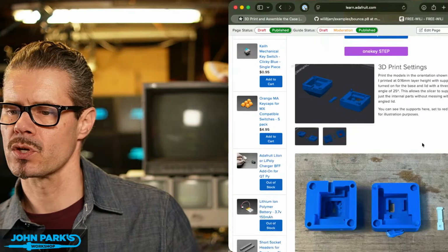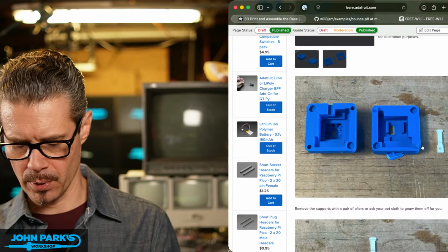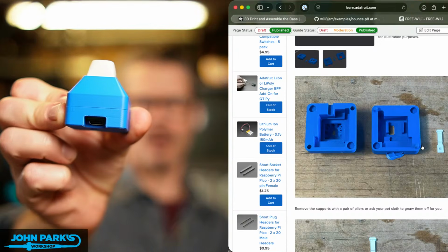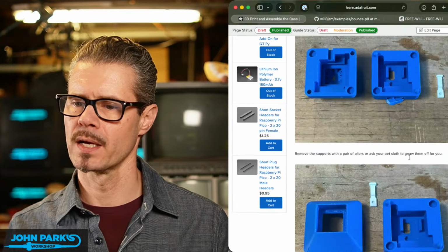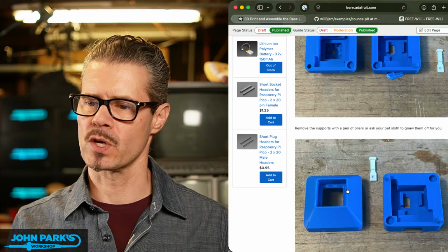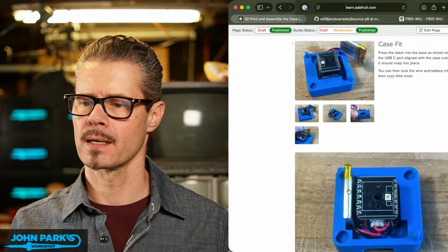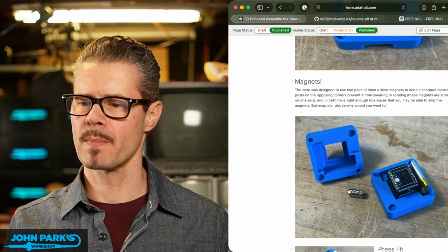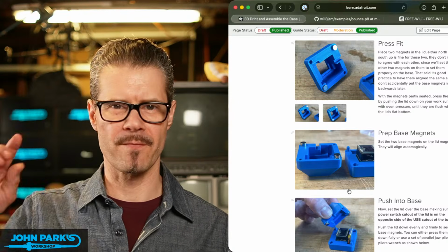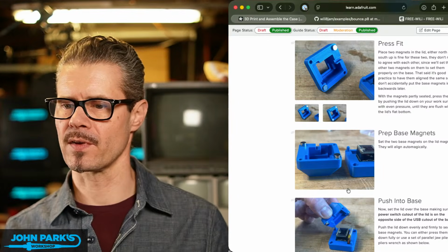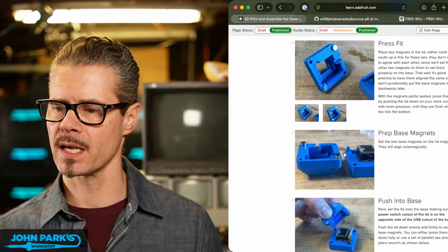So those are your settings, those are the parts. I used a little bit of tree support to keep that little arch there from collapsing, and same with one bit on the other side for where the key switch snaps into. And then we fit it all in and insert magnets. You just want to be careful about your orientation on those. So I fit 2 of them in and then set the other 2 on top, flip it over, squish it, then you know you're not going to have a magic levitating case.